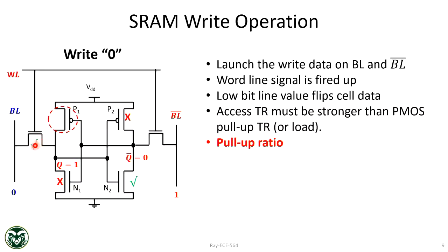If you don't size them properly, let's ask this question. Suppose this access transistor and PMOS are sized equally, meaning the W by L ratio, which is the size of a transistor, is the same, for example. Do you think write will take place?